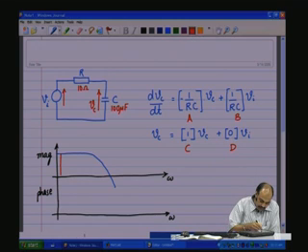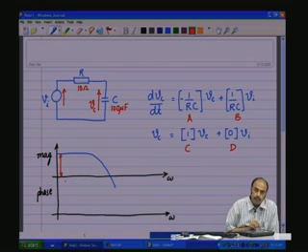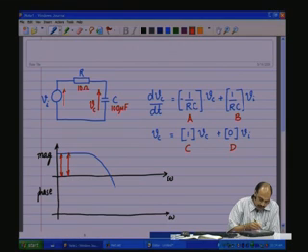You see that there is a specific amplitude at this particular frequency. What it basically would mean is that if you apply an input, this is normally given in terms of gain or attenuation in dB. The input gets amplified by this gain or attenuated by this particular gain, whatever it is at this particular frequency. So, you can get the gains at various frequencies, and as frequency changes the gains are varying.